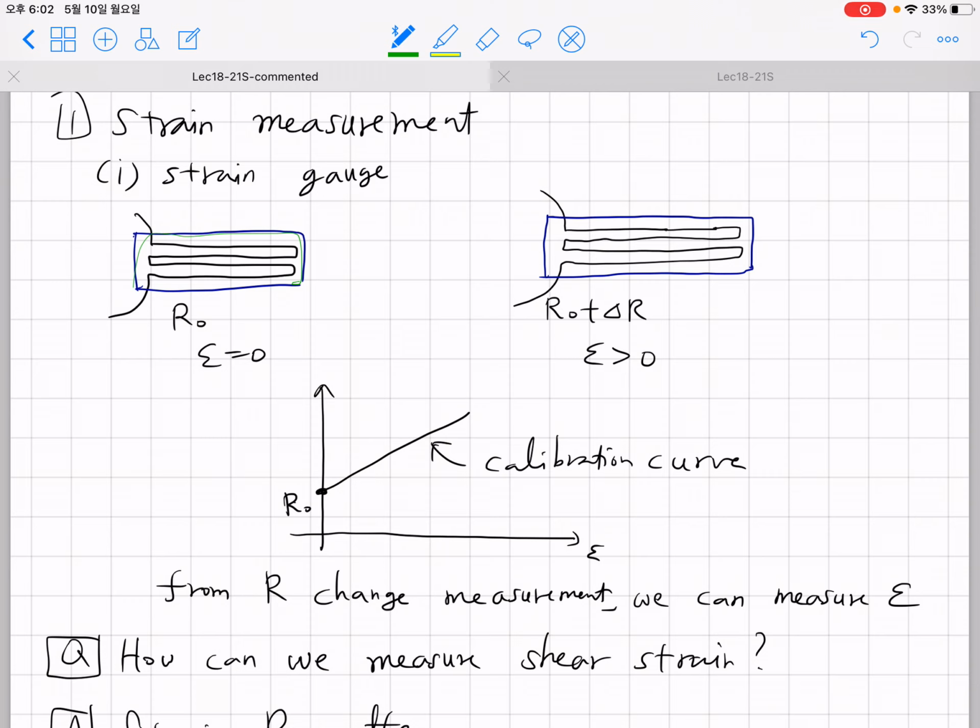thin material, where you have a quite long electrical path like this, and suppose that under thermal expansion or under mechanical strain, this entire structure would expand. Okay, so what you can expect is, along that direction, the wire would elongate too, and because you have a longer electrical path, the resistance would increase, right?